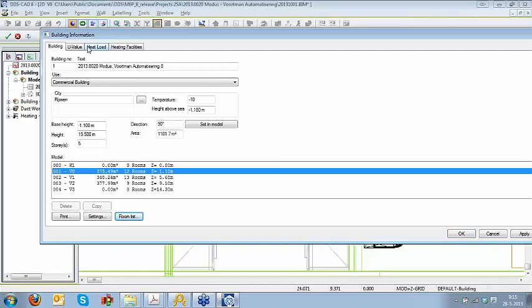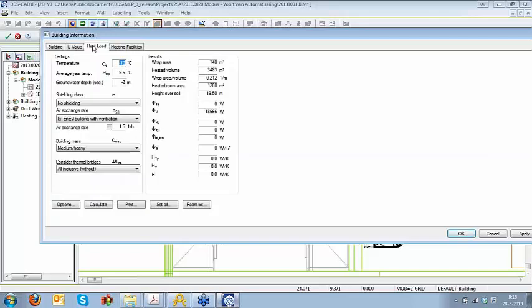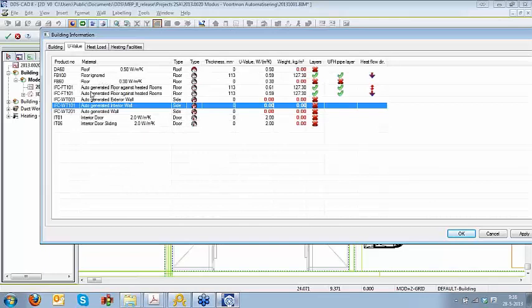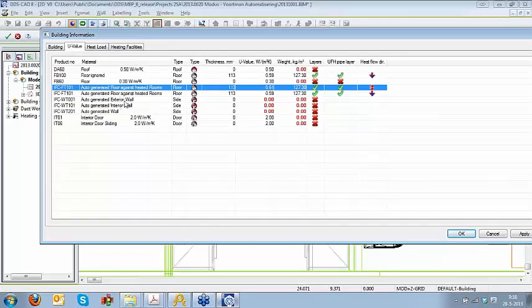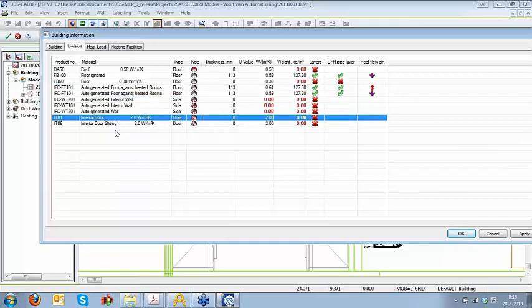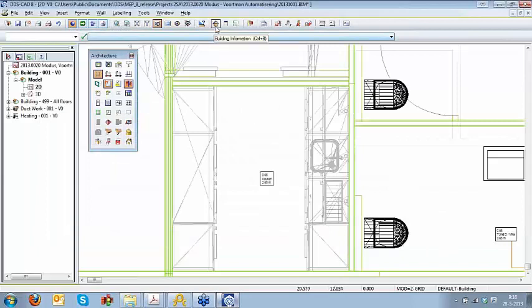All right. Inside this IFC file, we are using different objects which are recognized by DDS. Talking about heat load, there is a lot of information which is needed inside the room itself. So it's not only the name of the room, but also the values of the walls, doors and windows which are applied in the building model done by the architect. So we can see that the information is recognized from exterior walls and also recognized for interior doors and windows. So the information is directly reused and can be applied by a calculation directly on heat load.